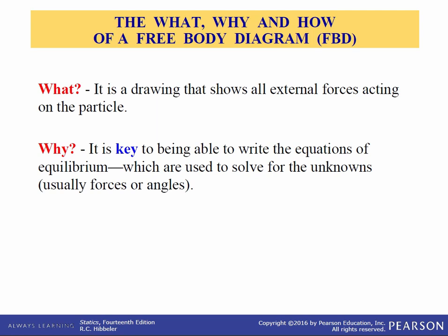Now, to apply the equations of equilibrium, we must account for all the known and unknown forces which act on the particle. The best way to do this is to think of the particle as isolated and free from its surroundings. A drawing that shows the particle with all the forces that act on it is called a free body diagram. Free body diagrams are one of the most important things for you to know how to draw and use for statics and other subjects such as dynamics and strength of materials.